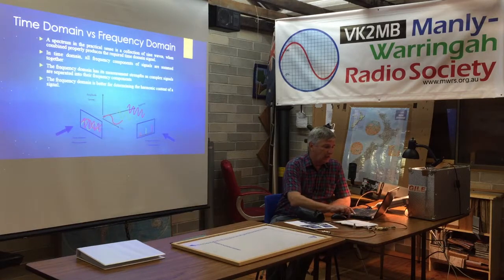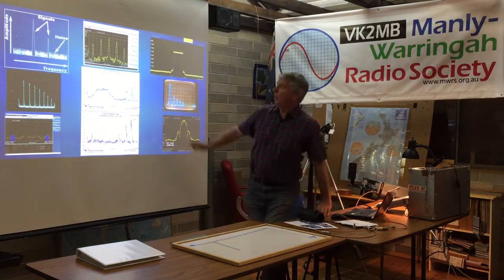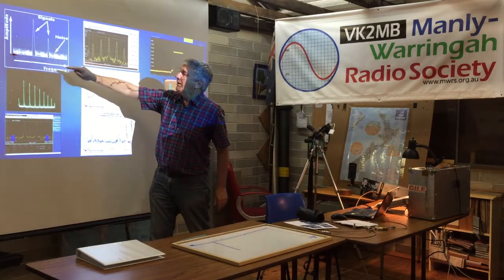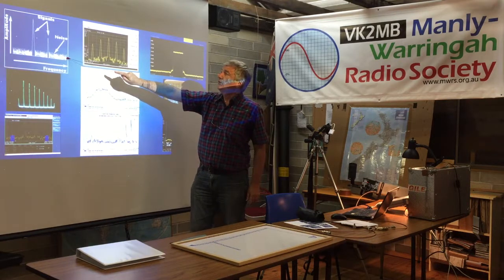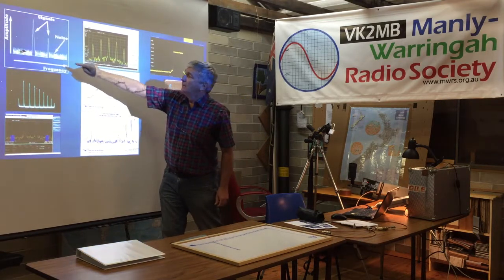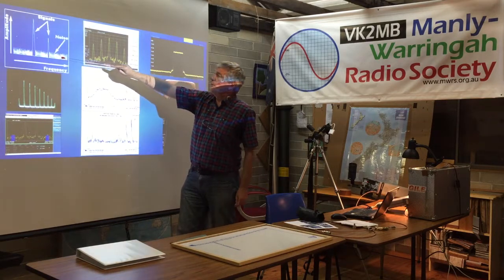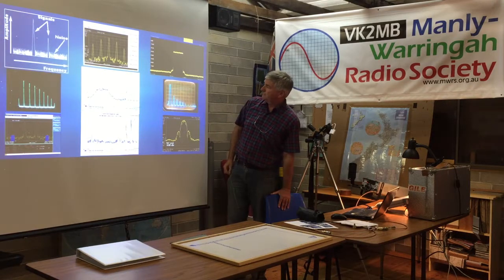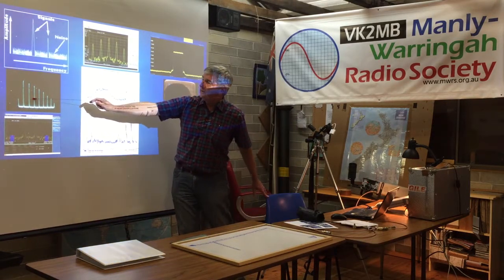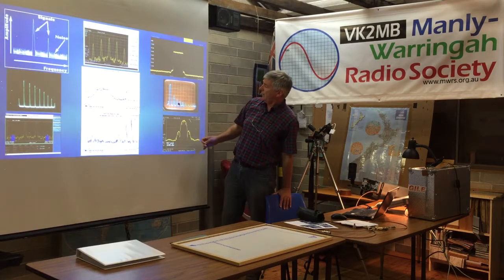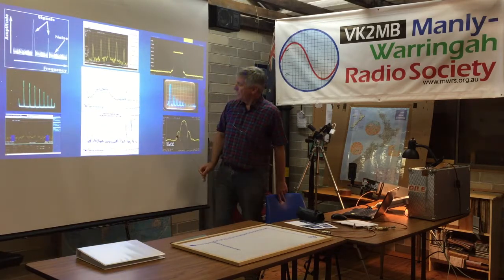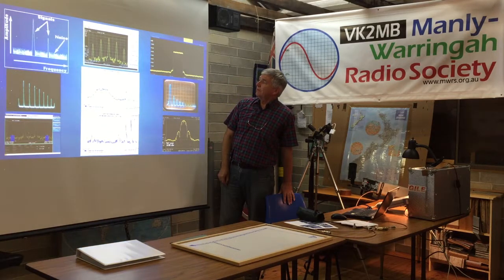And so again, just looking at some screen snaps of what spectrum analyzers look like. And again, this is what I was trying to explain. Amplitude is on this axis and frequency is on this axis. And we can see we've got two signals here and we have inevitable noise at the bottom here. I've just grabbed a few different snaps, the old CRT analog type displays versus some of the more modern displays. They all show the same thing, just in different ways. So that's what a spectrum analyzer is all about.